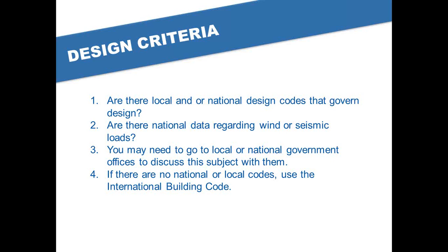I've had more difficulty actually with wind loadings, and there it's more difficult. Generally, it's on a country by country basis, and you have to somehow find, either through local engineers or local government sources, what the governing wind loading, or wind speed for design, is in that country.